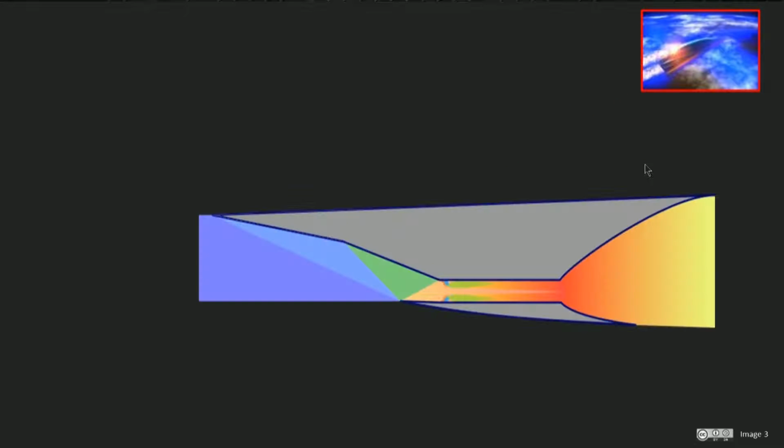Now let's imagine we are flying through the Earth's atmosphere on this scramjet vehicle. From our point of view, we are stationary and the air outside the engine is rushing into it. Just outside the inlet, these air packets are in a good and happy state where the pressure and temperature are quite pleasant. Now along comes this big, mean scramjet engine that swoops them into it. As the air packets travel through the inlet, they start experiencing the oblique shocks that you learned about in earlier sections, which compresses them. The pressure and temperature starts rising, and they now start feeling quite uncomfortable.